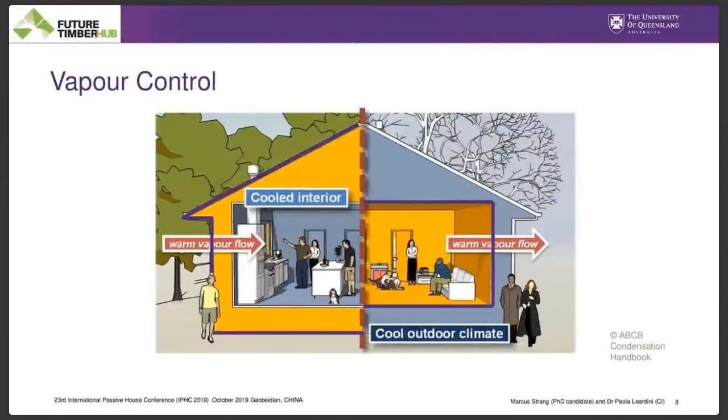And so we can see again, usually this presentation would kind of build up slowly when I click it. On the right-hand side, we have a European cold climate where I've highlighted the interior wall, and that's where we want to have our vapor membrane to prevent interior moisture from infiltrating the wall system and condensing against any cold elements as it moves outwards.